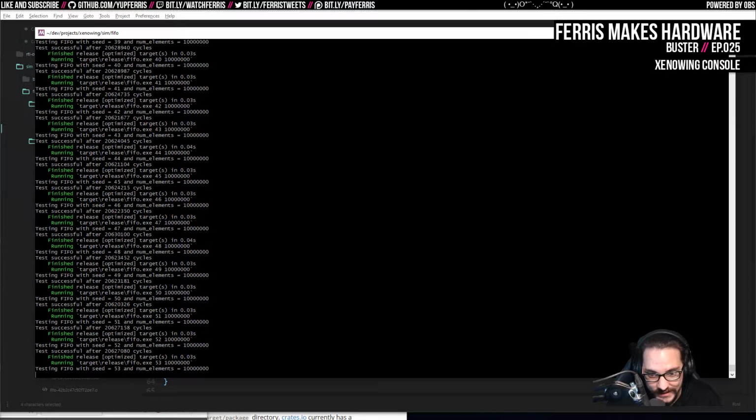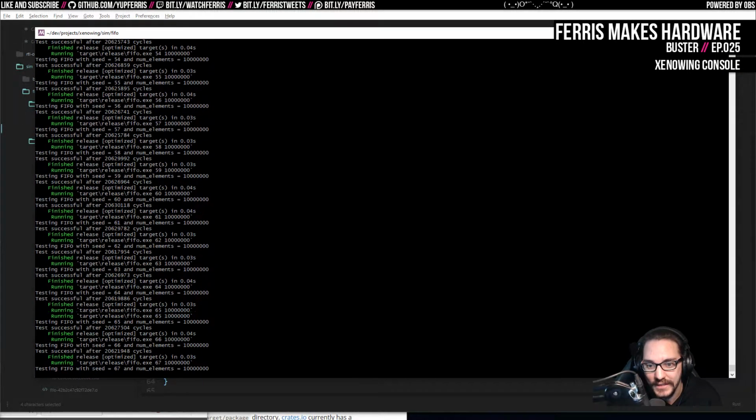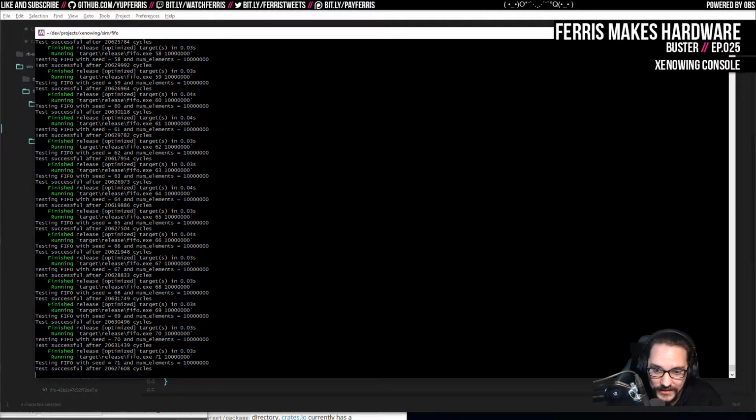So this is purely a latency improvement in the cases where we're going to use the Fifo, not a bandwidth improvement, because if the Fifo were actually saturated, or if we had a constant stream going in and a constant stream going out, then it would only subtract a single cycle of latency, which I think is also why we don't see that the cycle counts have changed. I don't think I ran this before I made this change, but the cycle counts roughly looked the same.